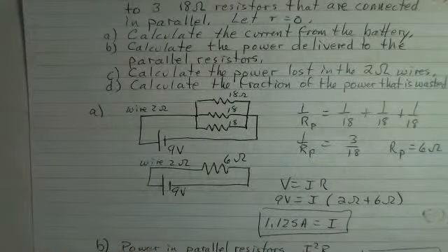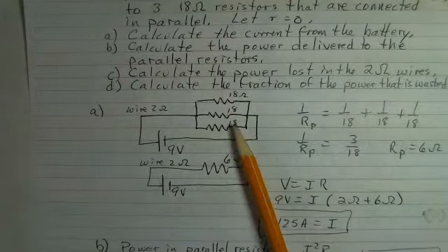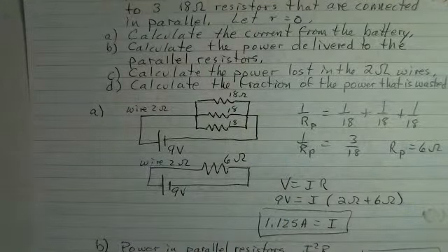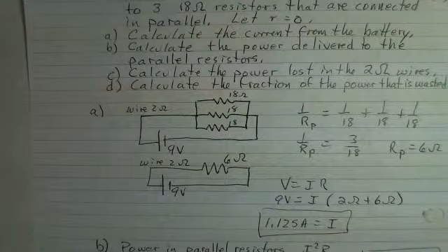Again, work on this general principle of reducing the circuit, making combinations of parallel and series where appropriate, and then calculating the current out of the battery, and then work your way back to finish your analysis of the problem.